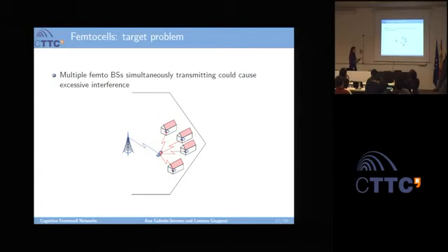So we go back to the first slide, and the idea here is that we know that the femtocells are randomly deployed, and we will probably have a lot of femtocells. A lot of people said that we can consider femtocells as isolated systems due to the wall penetration and the low power transmission, but if we have densely deployed scenarios, the aggregated interference that they may generate in potentially close macro users can be high.